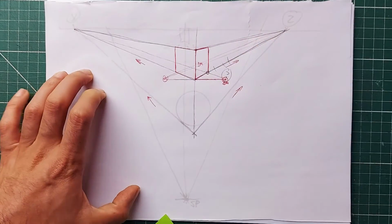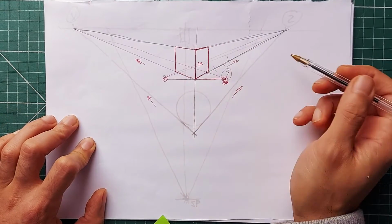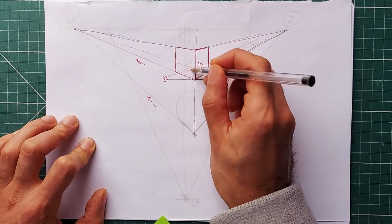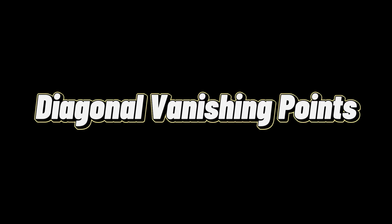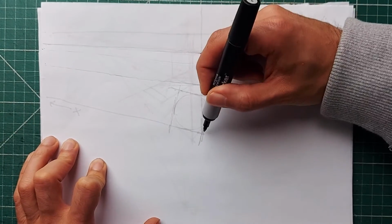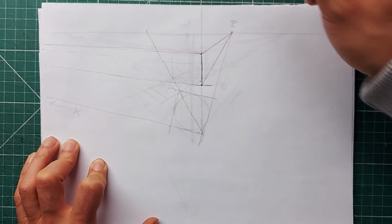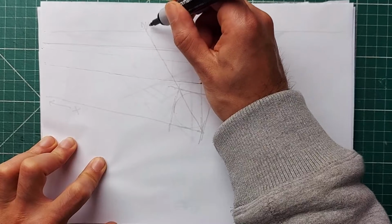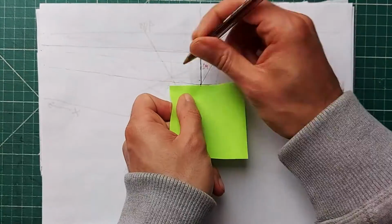But there's an issue here. Once again, we cannot tell exactly where the back edge needs to be placed to make this a perfect cube. You may remember that we achieved this previously in 1-point perspective by using a diagonal vanishing point. In 2-point perspective, we can do the same thing. We pick 2 opposing corners on our square in plan, and we draw through them until we hit the horizon line. This is now the spot that all of our perspective squares in this orientation will aim for diagonally in order to make our floor grids.